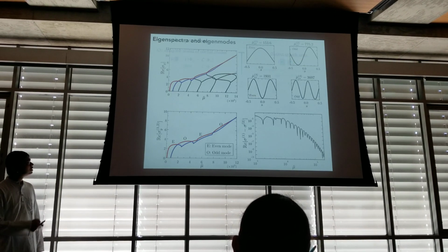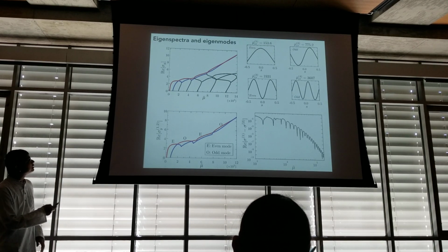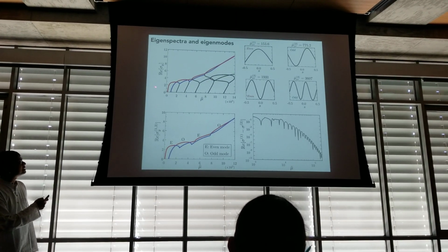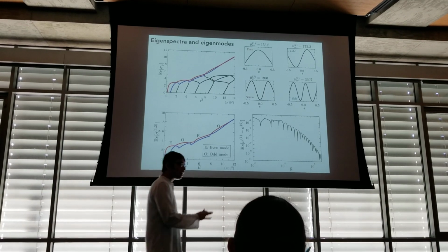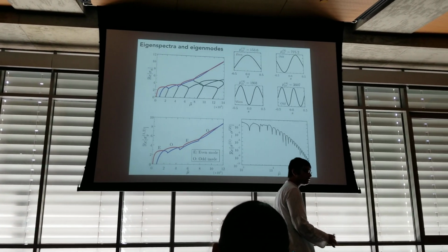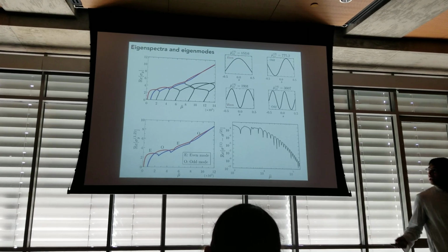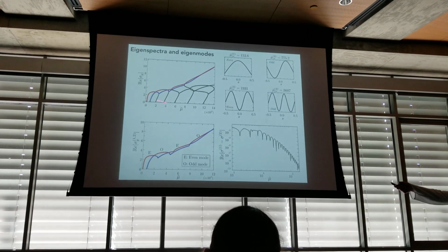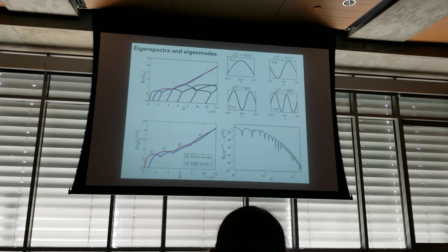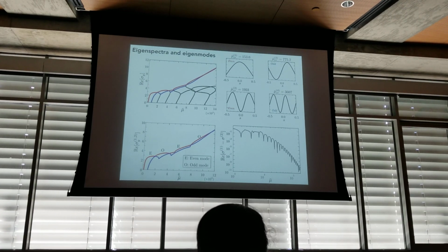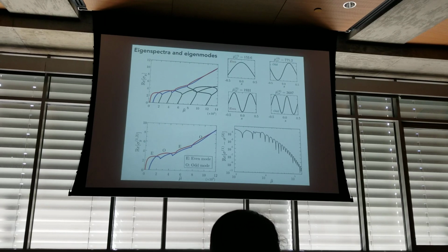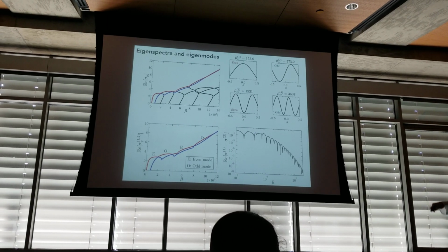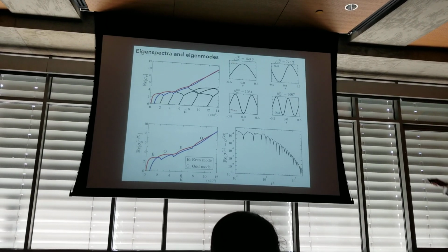So you expect the in-plane perturbations to get forced more and expect them to grow faster compared to the out-of-plane perturbations. So you can solve this problem numerically, and this is the eigenspectrum for the in-plane problem, that's sigma y that I'm plotting over here. And let me re-emphasize that the eigenspectrum for the out-of-plane problem is exactly the same, it's just shifted by unity. Now as you increase your flow or control parameter, there's a critical value at which one of the eigenvalues becomes positive, and that's a pitchfork bifurcation or the onset of Euler buckling instability. And associated with this instability is this classical C-shaped buckling mode that you see over here.